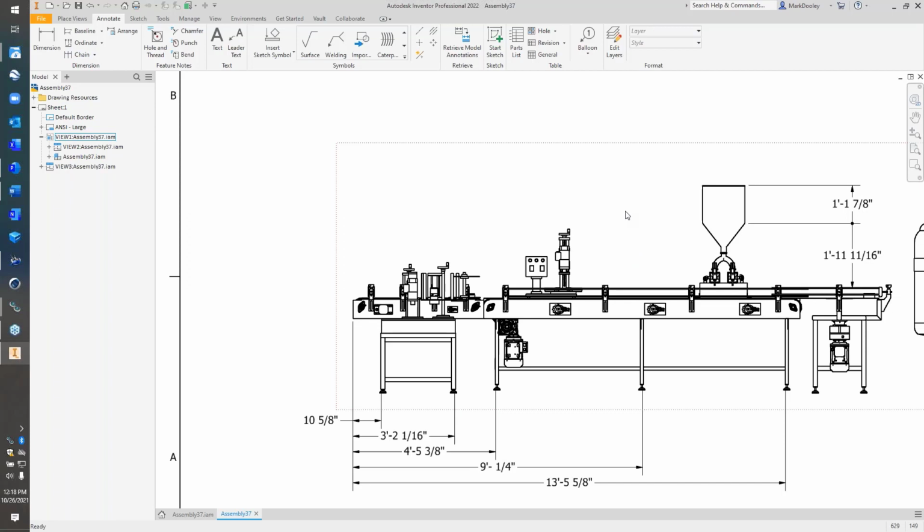So again, this was introduced back with Inventor 2016. It's been there. Some users know it's there; for some companies, it's new to them. Depending on which release you're coming from depends on what files can be translated, especially on the Inventor side. It can only be one release newer. If you've got Inventor 2020, it'll work with SolidWorks 2019 and older. Inventor 2022 will work with SolidWorks 2021 and older.